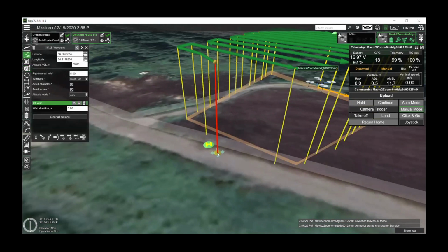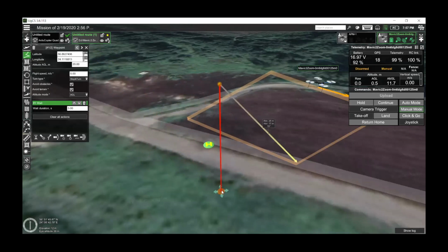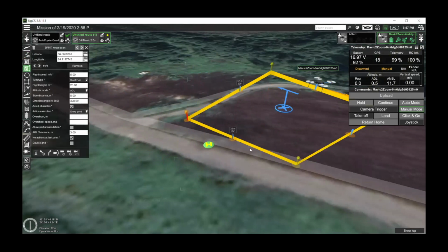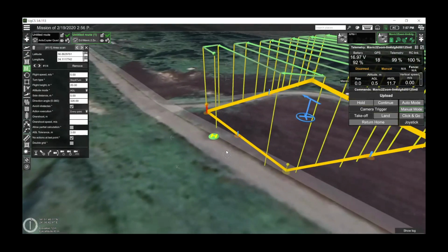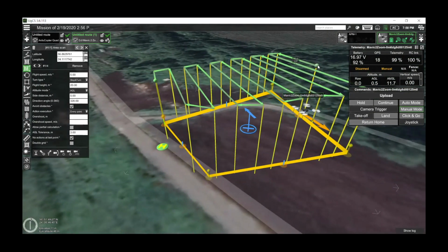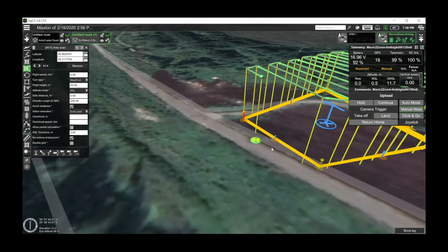This route which I just showed, I will adjust now the first waypoint. If you create a simple waypoint as the first one, you can freely move it around. If it were an area scan, it wouldn't be so easy. So in the case of an area scan, now I will delete my simple waypoints. I left only the area scan. In this case, the area scan starts from the opposite side. But for example, I would like to launch the drone from this home location.